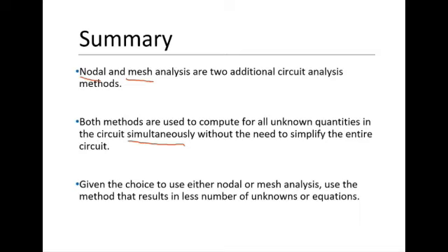Given the choice to use nodal or mesh, the pro tip is to use the method with fewer unknowns or equations. Okay, so that's the end of this lecture.